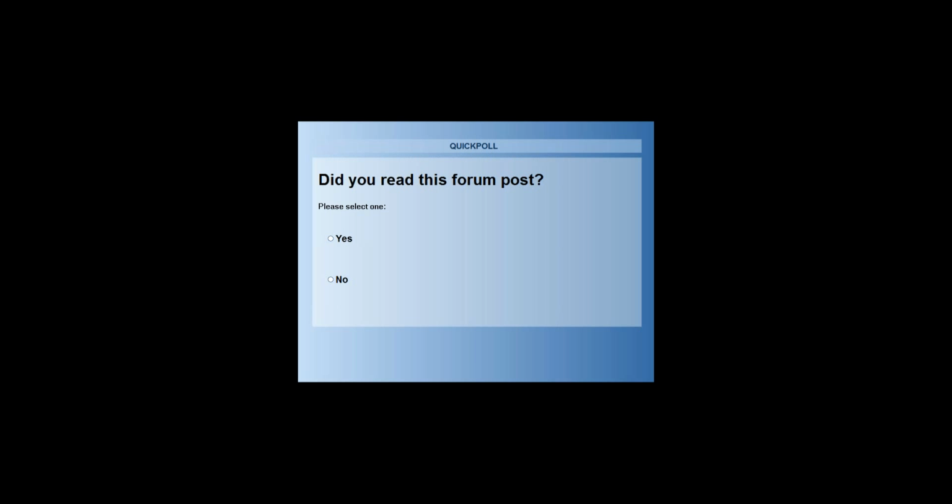You don't want to keep changing your settings. I think when you look at the trends of our results, it fits very well until we reach a stall condition where there's a lot more turbulence in the model. So I think when you start getting to that past stall condition, we might require more mesh. We might require maybe to run transient to be even accurate because of wake conditions that could start forming. It's not really steady anymore. But otherwise, no. The simple answer, not really.